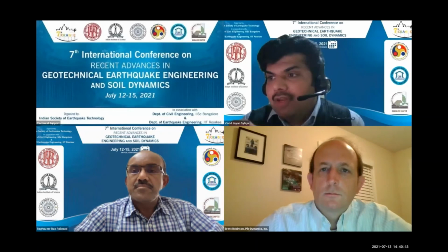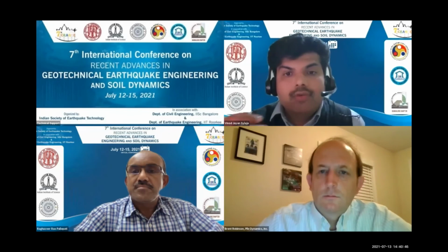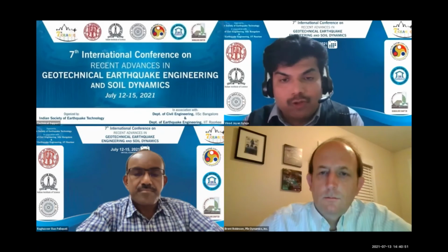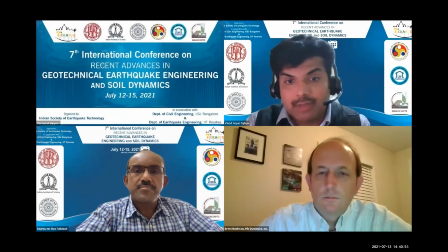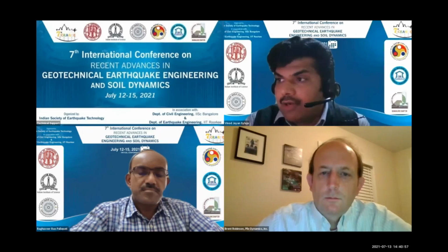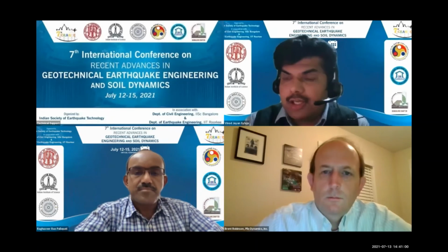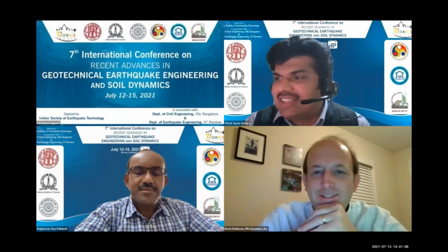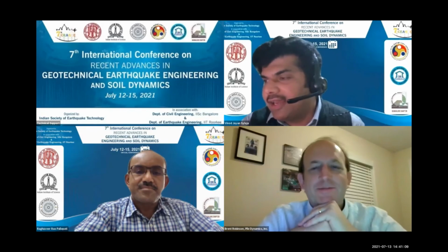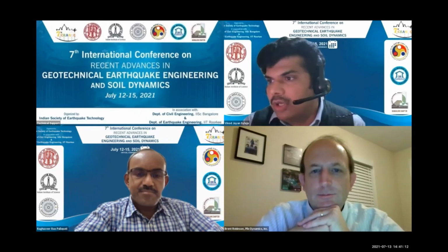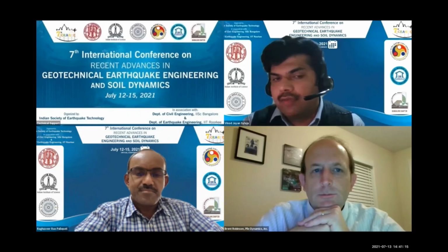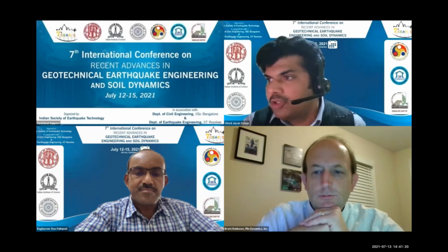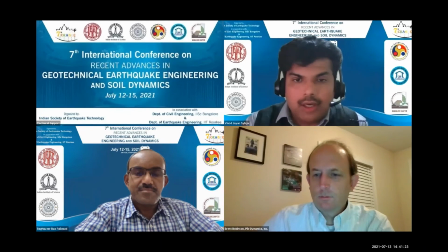As I have told you, very little work has been conducted in this area, even to look at, for example, the effect of aperture size on the reinforcement effect, or the filter or separation effect of this material. In this study, as I have clearly highlighted, as a plate element in a 2D phase, we cannot capture all those aperture effects in the model. So we have not gone to that area. This is just a beginning to look into a more realistic goal in the future, to see whether we can come up with a robust model to capture some of these key factors.